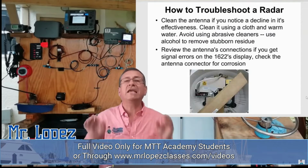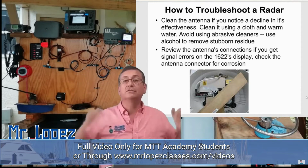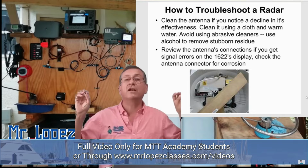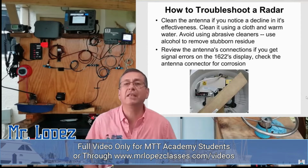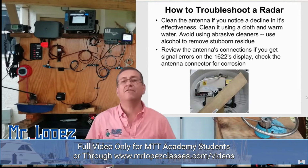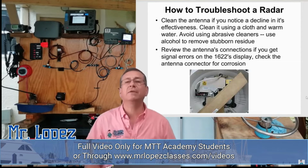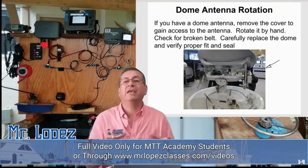Use basically isopropyl alcohol to clean the ends of the sensors. You remember I explained the ends are plastic containers to protect the infrared sensors located inside. You need to clean that plastic with isopropyl alcohol. Never clean those terminals with acetone. Never clean those terminals with bleach. Clean those plastic terminals with isopropyl alcohol. That's the procedure. The dome in the bottom has an O-ring. Be careful with the O-ring.